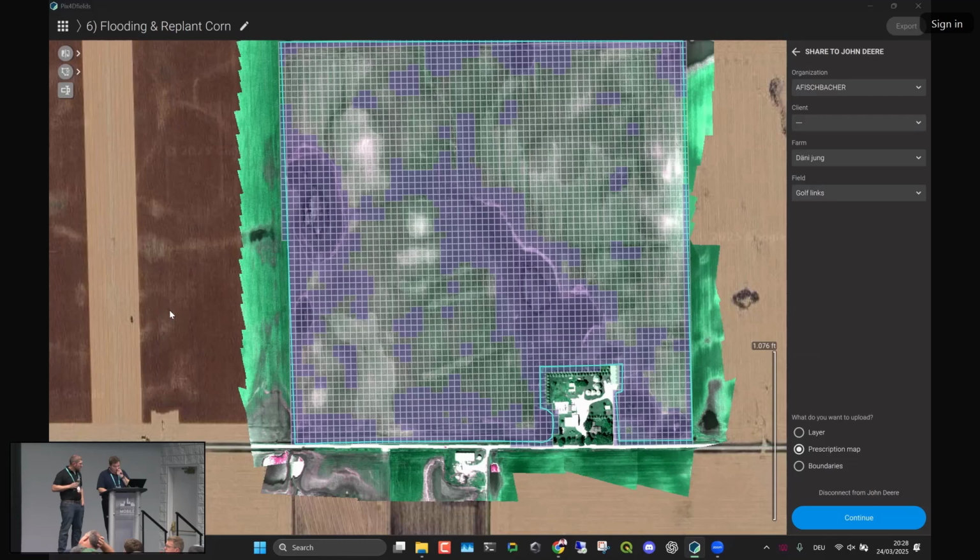Here's another question, an RTK question. For an RTK workflow, do you need to upload anything special when processing, or is the RTK data embedded into the picture file? This is very drone specific. On the Mavic 3 multispectral, which we talked a lot about here, it's already tagged in the photo if you turn the RTK on. Remember that you have to flip the switch up in the top corner. If you don't, it's not RTK. Just because you have the RTK thing on top doesn't mean it's RTK. It means you still have to connect to that RTK base station somewhere.